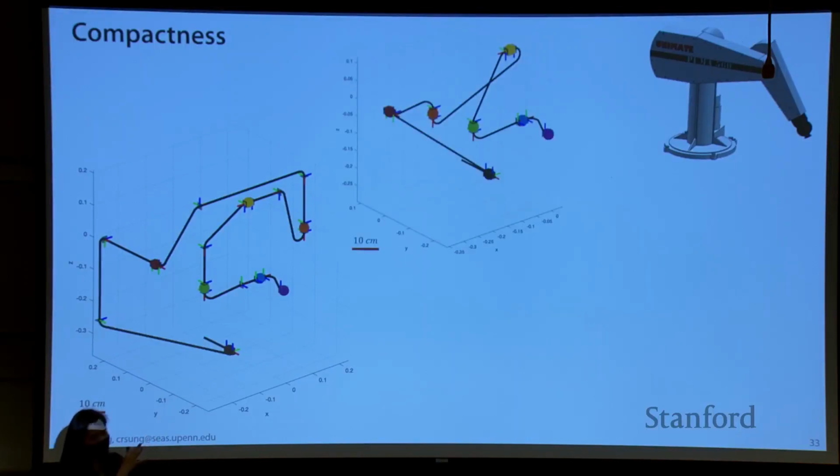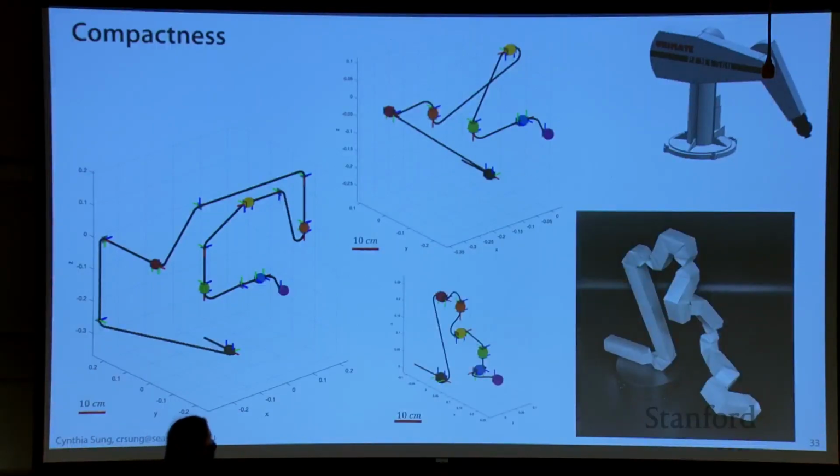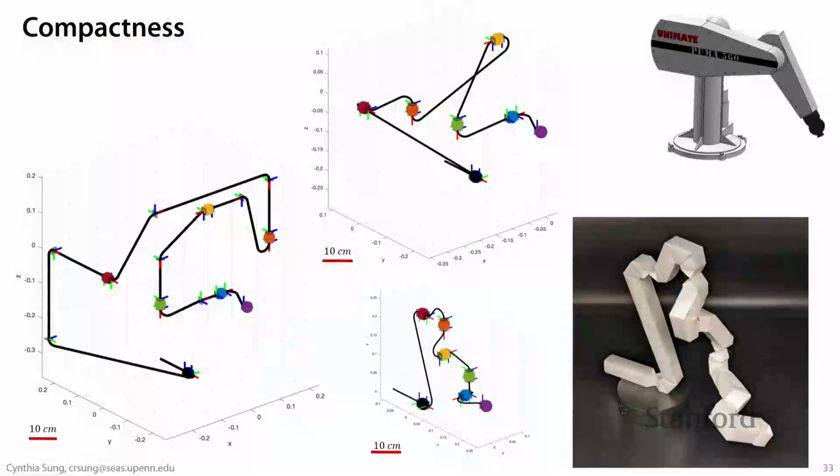If we drop some of the constraints that are needed in order to avoid self-collision, we get a structure that looks like that, and these are at the same scale. And if we add a human in to actually place all of the links for us, then we get a nice complex Puma arm equivalent, which then we can fold into an arm that looks like that. So essentially, what we have shown now is that at least in the space of manipulation, we can get an arbitrary kinematic chain with a desired compliance profile out of a modular design approach.